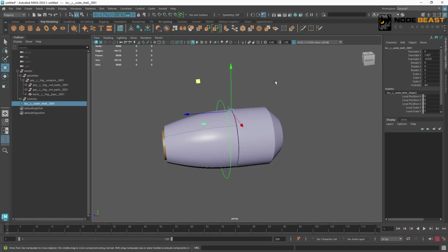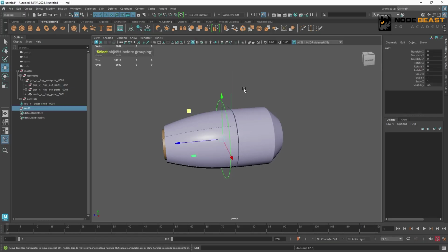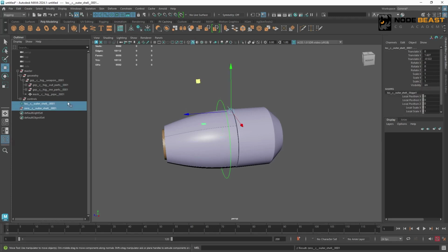But we generally don't freeze transformations. Instead, we create a group. This is the same logic as when we did the aim constraint exercise. Name this group 0, snap it over, then put the locator inside. This way, you see, it no longer has these values itself.